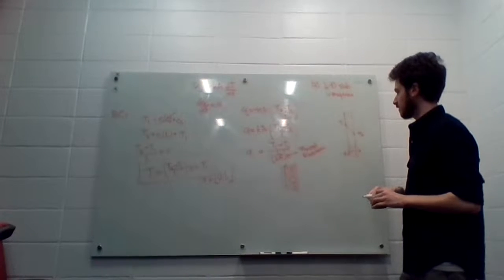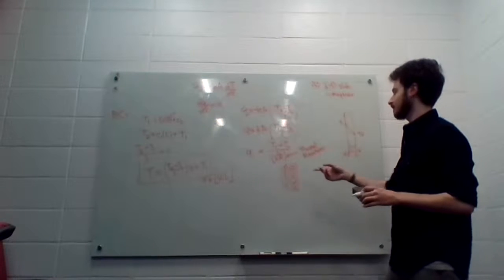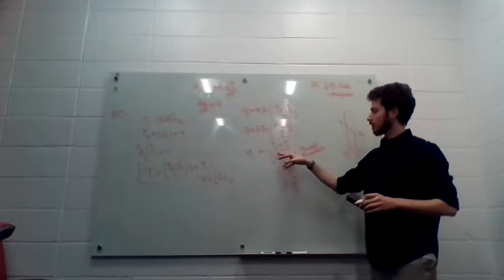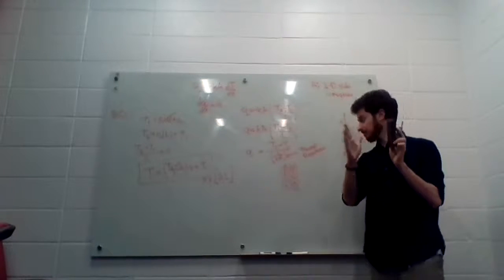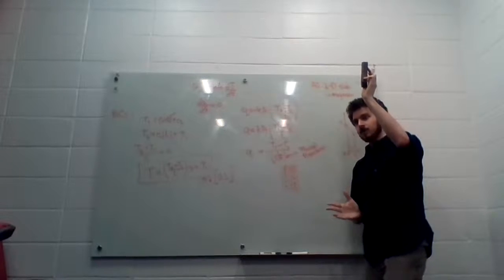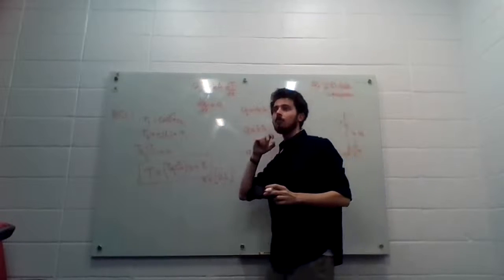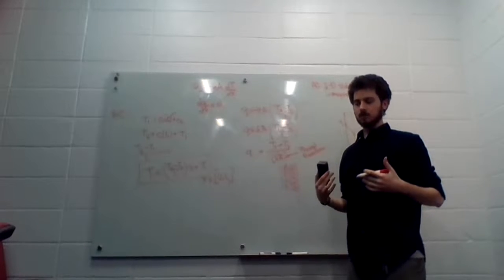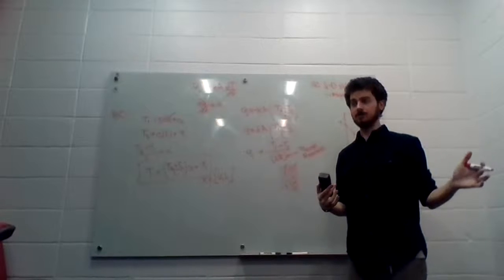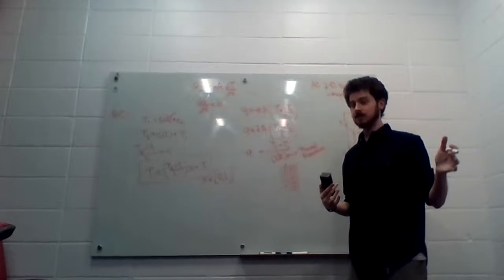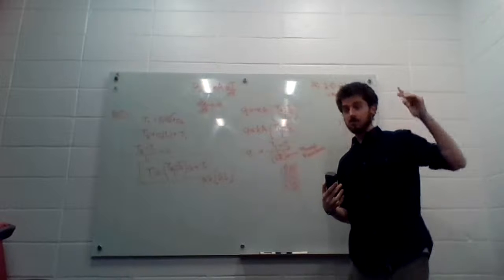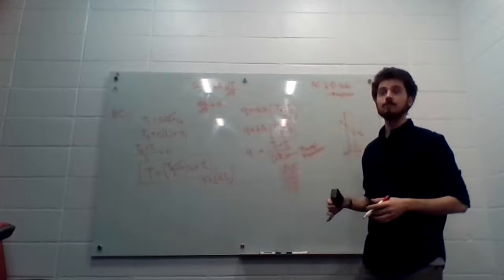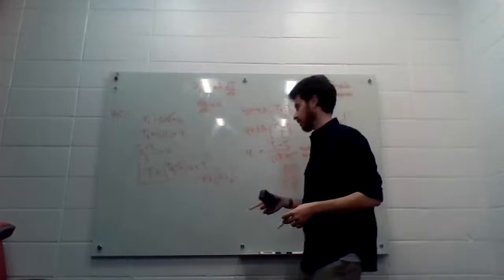This is your thermal resistance. Basically, the point is once you've defined the thermal resistance for a material, say I've got a piece of gypsum board, I know it's 1/2 inch thick, I know the thermal conductivity, I know the area, that applies whatever temperatures I plug in. I can plug in 20 degrees Celsius inside, about room temperature, and 0 degrees Celsius outside, that's freezing. I could plug in 35 outside and 20 inside, and I'll get a different direction of transfer, but I can compute it all.